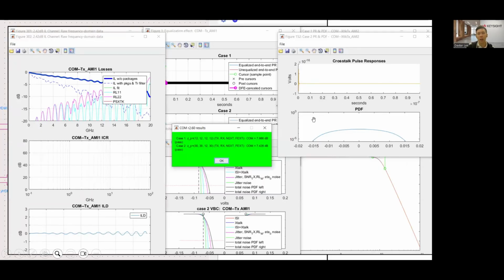I think there is a common measurement feature in channel operating margin called the ERL, effective return loss. I think that's crucial usually in Ethernet applications. So that ERL is also simulated using the channel operating margin. This is something that we do support as well if you are looking at Ethernet applications.